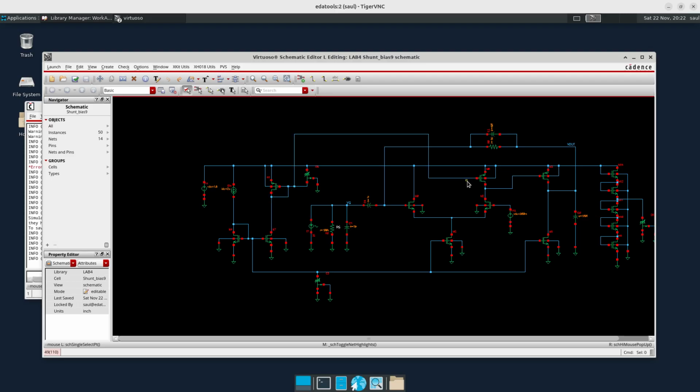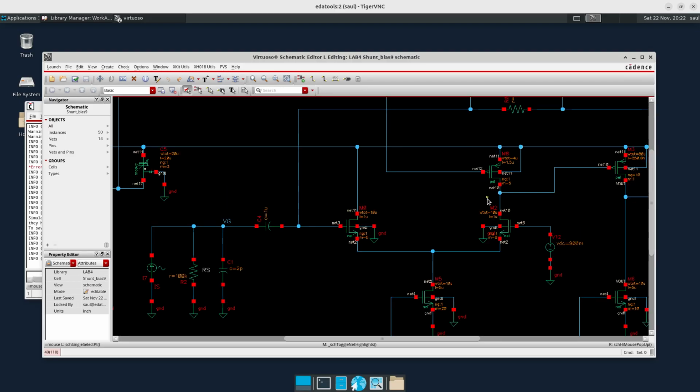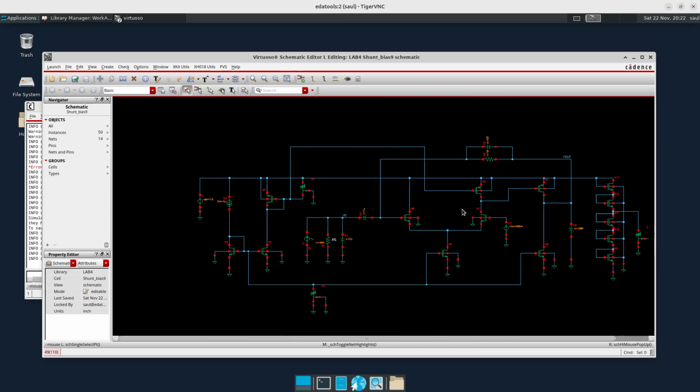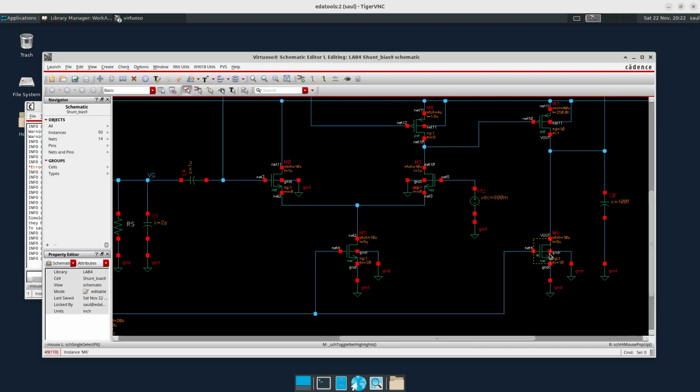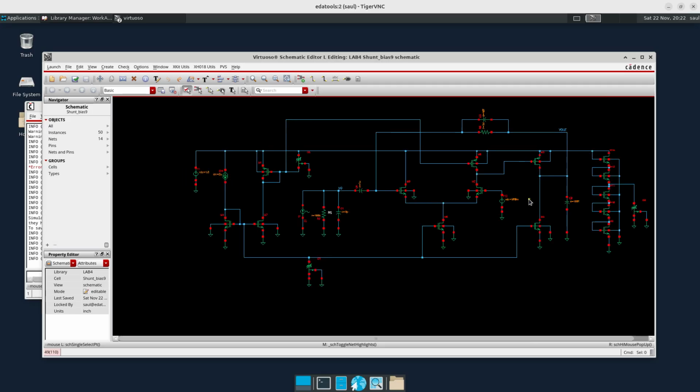And what is important here is basically to make sure that when we create these current sources, they have enough output impedance and that they are not contributing too much capacitance. Another extremely important detail is that when we put the transistors here, the current mirrors, due to the capacitances, there is going to be capacitive coupling between the output.